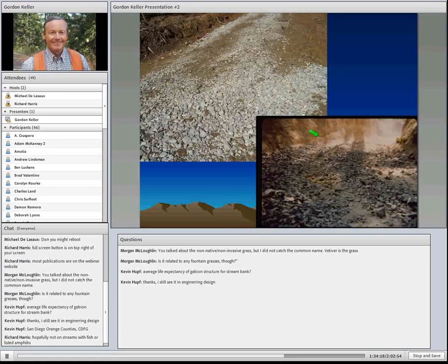Mixing coarse rock is something we use a lot in some of our coarse basalts here in the Sierras, where you're taking just the pit run rock, putting it down on the road, which is hard to live with, scarifying and mixing in just a poor man's road mix, so you've got some fines mixed in with coarse rock, and it's something that's drivable.